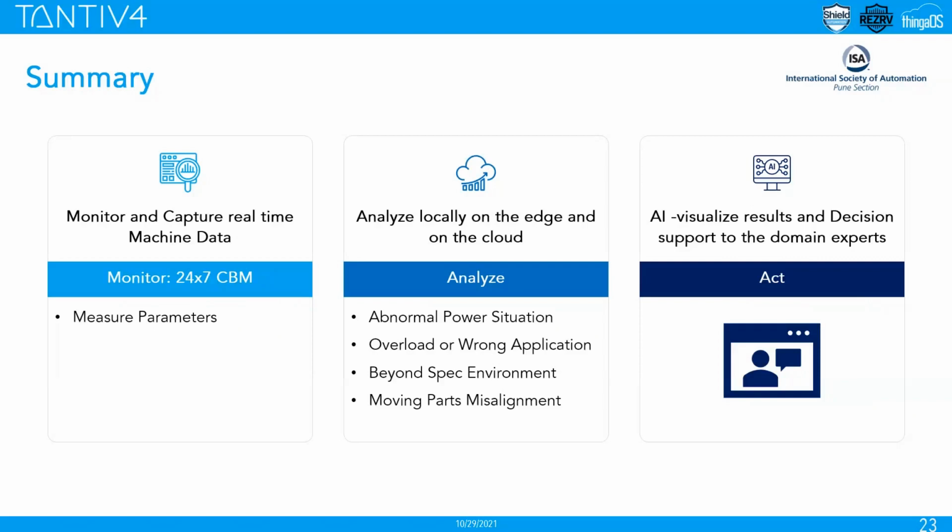That is very important for us to monitor, so that he can take action on the faulty parts in the looms. By looking at the harmonics, you can see the frequency and the loom speed. You can relate with that and find which gear or which moving part is creating the problem.